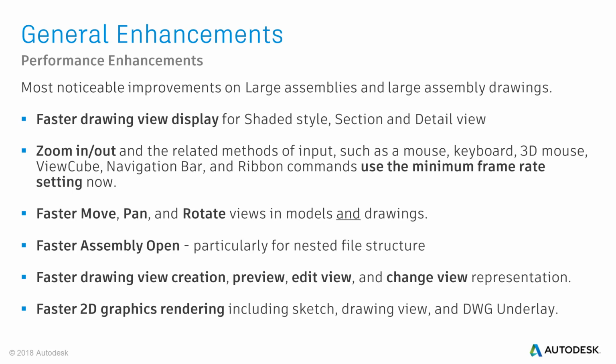Zoom in and zoom out now use the minimum frame rate setting as well. I think you can see all possible methods of how you can get a zoom on the slide. Most interesting for you should be the faster zoom behavior is also supported for 3D mouse devices. You will also notice there is a faster move, pan and rotate behavior for views in models and drawings. The assembly open behavior has been improved, particularly for nested file structures.